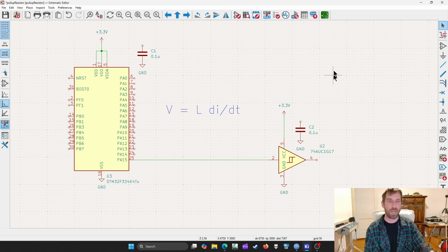One is so I don't have to worry about the rest of the circuit, what else is going on, what else is on my board, and all that. And then item number two, this thing's like a penny. So it's just not a big deal just to add one and just put it close. So I don't want you guys to be obsessing over this stuff anymore. Just look at your data sheet, what it recommends, just do that, get it kind of close, and then you will be good in most cases.